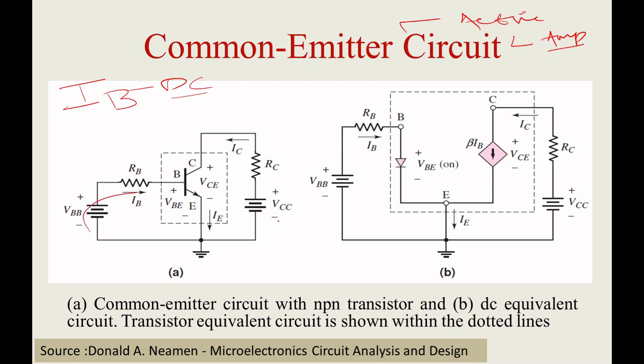This is also a conventional current direction, going from the collector, from lower potential to higher potential. You can see two currents are entering and the emitter current is leaving. So the emitter current is nothing but the sum of your base current and collector current. You have to be very clear on that, my dear friends. This is your junction voltage and this is your output port. This is junction 1, this is junction 2. Base-emitter will always be forward biased and collector-base will always be reverse biased, keep that in mind, don't forget.